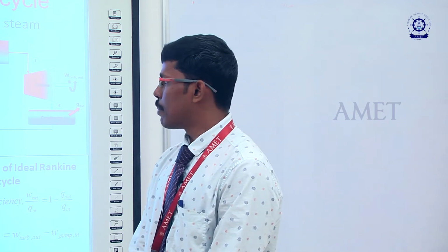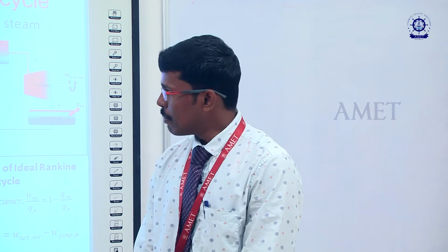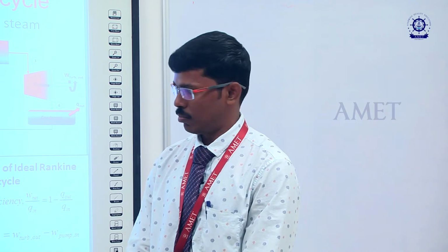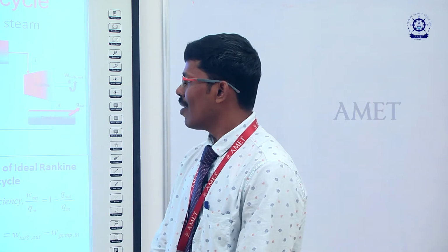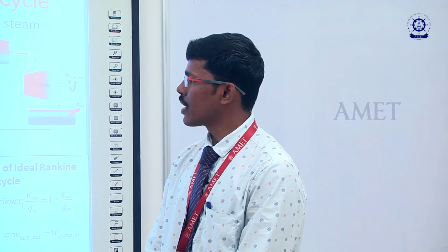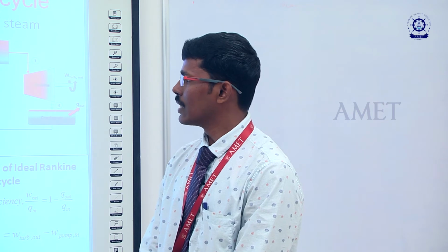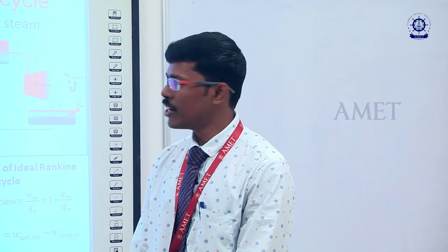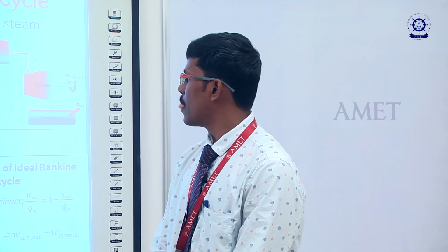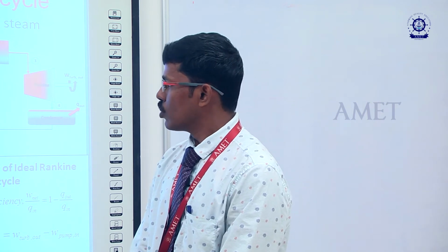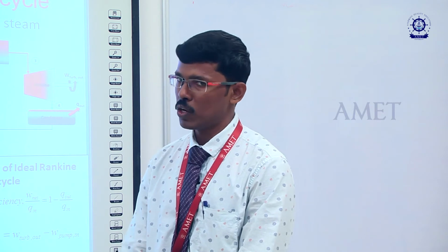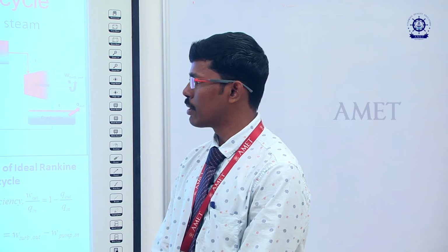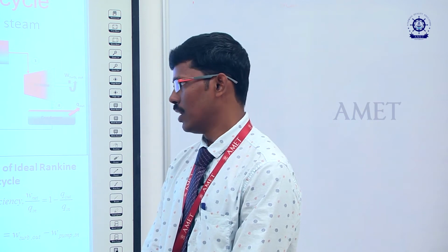Let us consider the pump. In the pump the work is given to the system, so there is no heat transfer, that means Q is eliminated from the equation. It reduces to the work of the pump, which we are giving to the system. The work input to the pump is given by H2 minus H1.